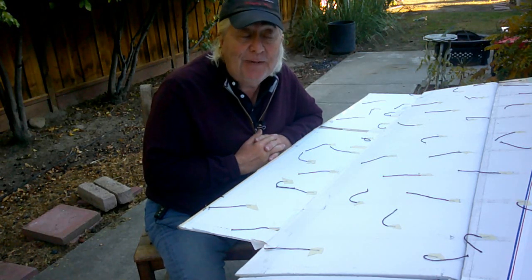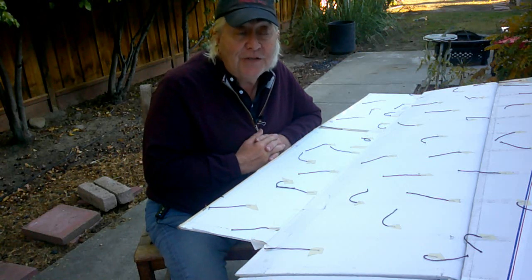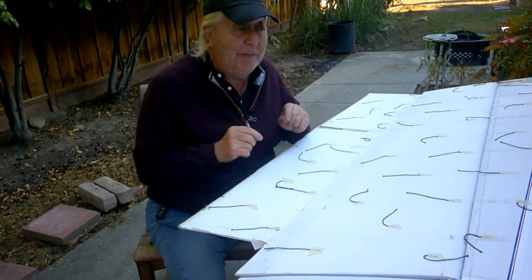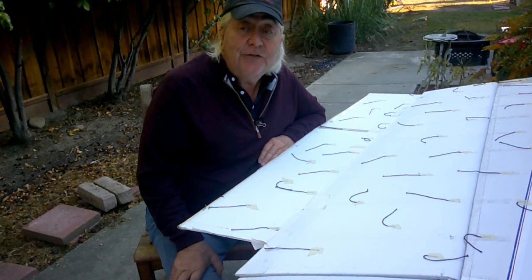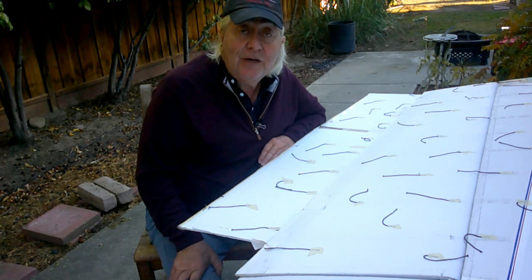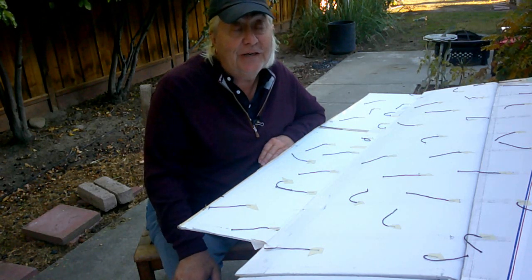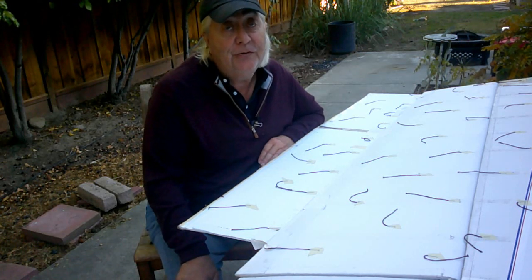Oh, is that the magic number? 36 inches? And I thought, no, the magic number is 500,000 on the Reynolds number. That's the magic number. So work it backwards the other way. At our standard stall speeds that we need for a foot-launchable aircraft, 20 miles an hour, just in round numbers, maybe a mile an hour less or more, but right about 20. At 20 miles an hour, how much chord do you need to get a Reynolds number of 500,000? And the correct answer at sea level is 32 inches.